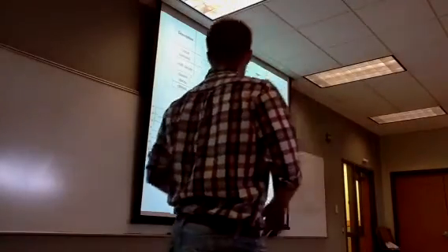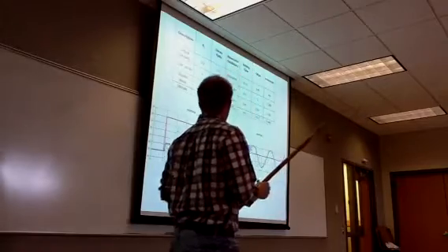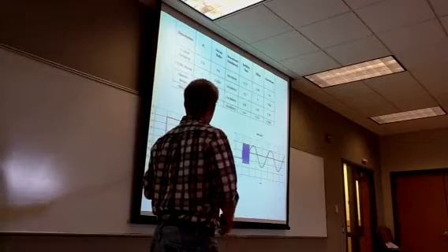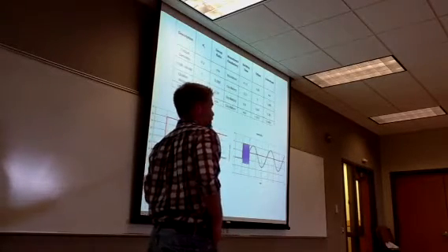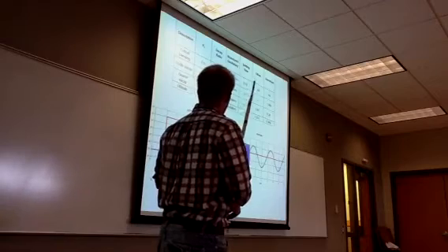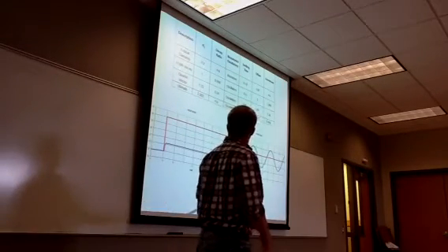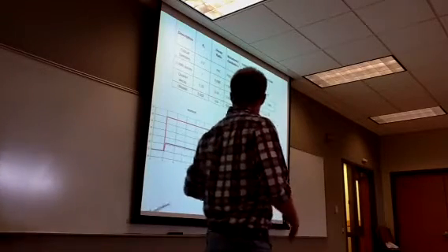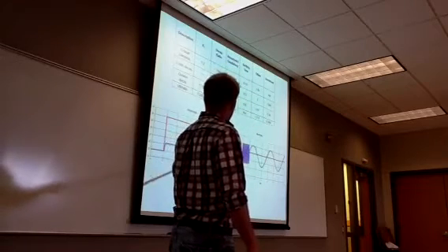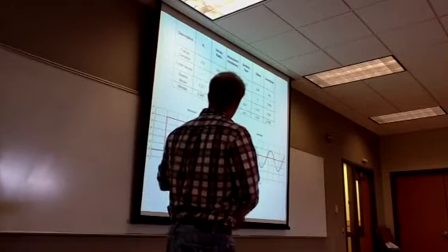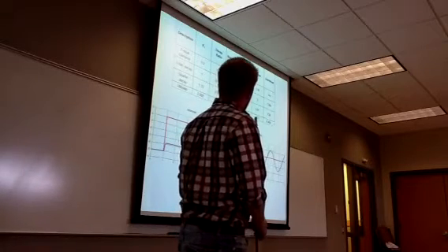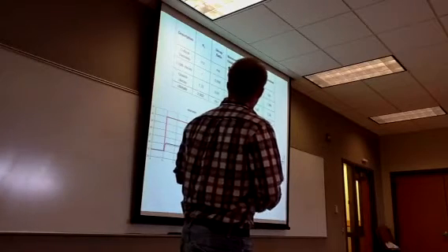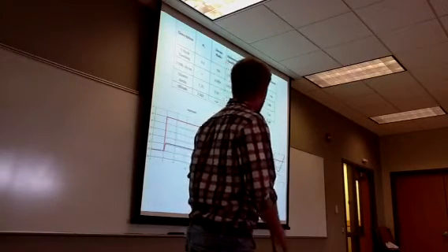From this, we got the proportional only experiment. This one right here is a critical damping chart that we got from the lab, and then over here is the ultimate damping chart. As you can see, the critical damping is monotonic, whereas the ultimate, and actually the rest of them, are oscillatory. And the ultimate will never settle out, whereas the rest settle out fairly quickly.